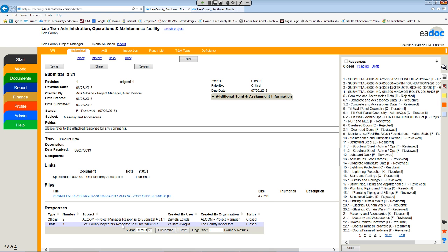Okay. Well, first of all, when the comments come in, if, for example, I send those shop drawings to the consultant, and I send them to ITG, I get comments on the shop drawing. If only one response comes back, fine, but if I have multiple responses, I read them and make sure the responses don't conflict with each other. Then I have the option to combine those responses, merge them together, and send the contractor one response.